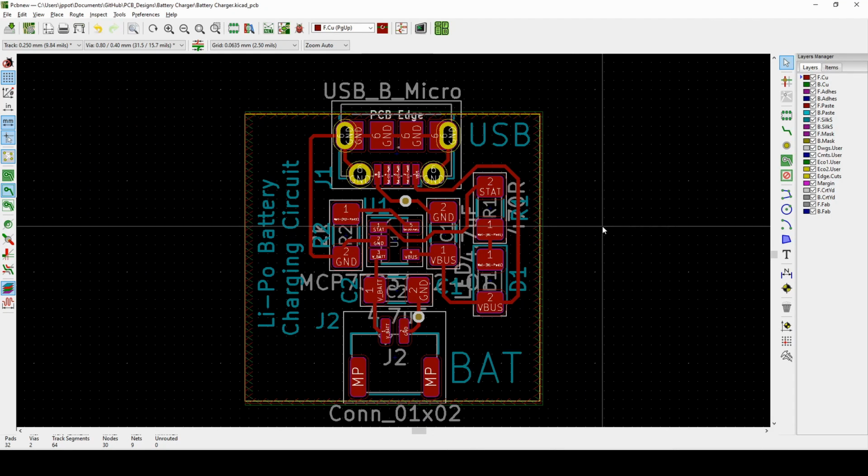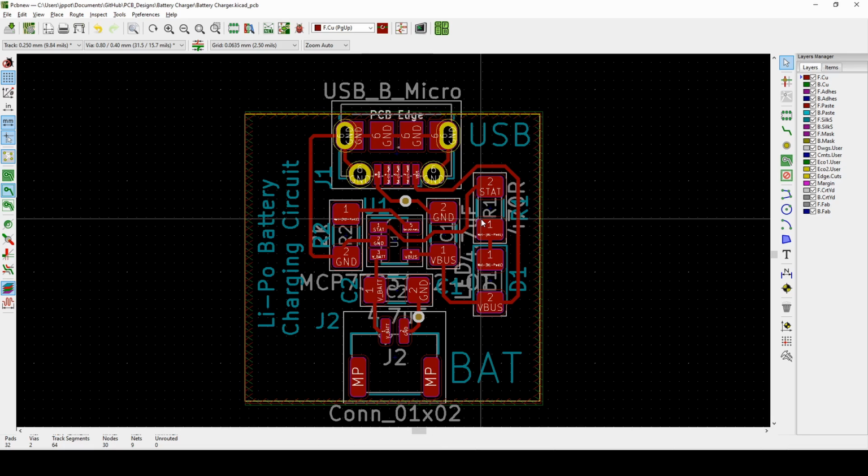So the manufacturing PCB requires from you is basically three files: the BOM, which is the bill of materials, your pick and place files, and the Gerbers of the PCBs. With those three, they'll be able to populate the boards for you and deliver a fully functioning board to your doorstep. So I'm going to focus on those three and then take you step by step how to generate all of that.